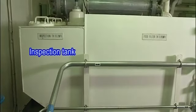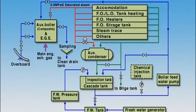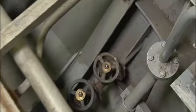The drain return line for heated steam has an inspection tank, which is located in front of the cascade tank. Check this tank regularly for oil content and other floating matter. Based on the results of boiler water testing, you can drain boiler water outboard from the blow-off pipe to reduce enrichment or remove impurities.